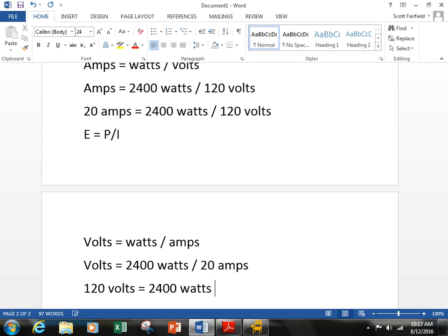So the biggest thing is, here's what's on the circuit. Usually you could plan ahead and say, if you've got a 20 amp breaker and the wire can handle 20 amps, then your devices plugged in cannot exceed 2,400 watts on that particular circuit. And that will go back to your service entrance panel, where you've got a breaker that's got 20 amps on it.